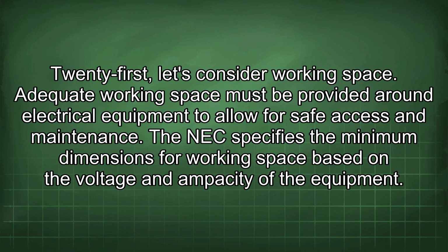21st, let's consider working space. Adequate working space must be provided around electrical equipment to allow for safe access and maintenance. The NEC specifies the minimum dimensions for working space based on the voltage and ampacity of the equipment.